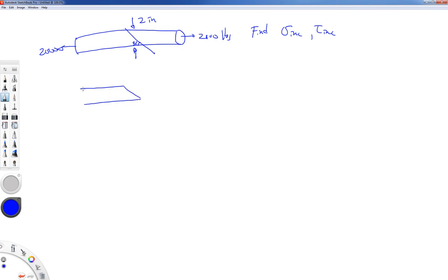If we look at a side view, it'll look like this picture. The free body diagram needs to be in equilibrium. So we have those axial forces that are equal and opposite, and then we want to break that force up into its normal and shear components, and this being 30 degrees in this case. So the angle from the horizontal to the slant is 30 degrees. Well, that's really easy. The geometry on that is really easy.